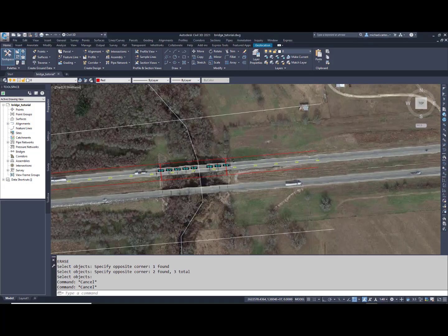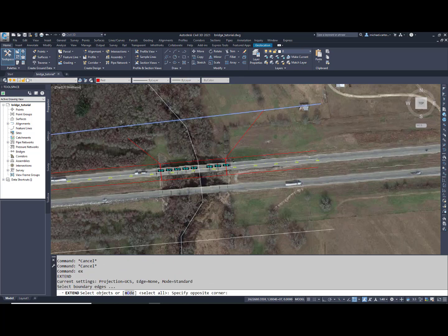In addition to the upstream and downstream bounding cross sections, HEC-RAS has guidance that recommends that the cross section upstream and downstream of those two bounding cross sections also take into account ineffective flow areas. Coming from that abutment on the approach, it is recommended a 45-degree angle for where that ineffective conveyance is flowing. So I'm drawing a line perpendicular, and then I'm just rotating it negative 45 degrees on one side and 45 degrees on the other side. This is mimicking a 1-to-1 expansion of effective conveyance.